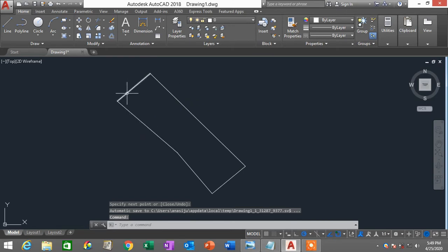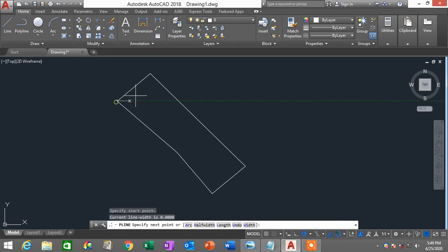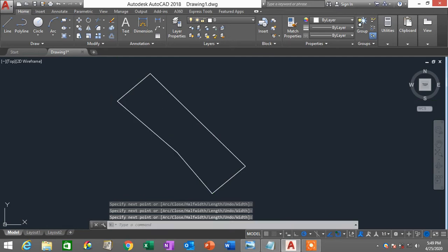You have now formed all these lines in order to create a property lot or the title boundary. You can also use a polyline to trace back all these lines. Click this, click this, click this, click this. If you use a polyline, all the lines are joined together. If I delete this polyline, you can see this is my original line, which is broken apart, broken into its own elements.